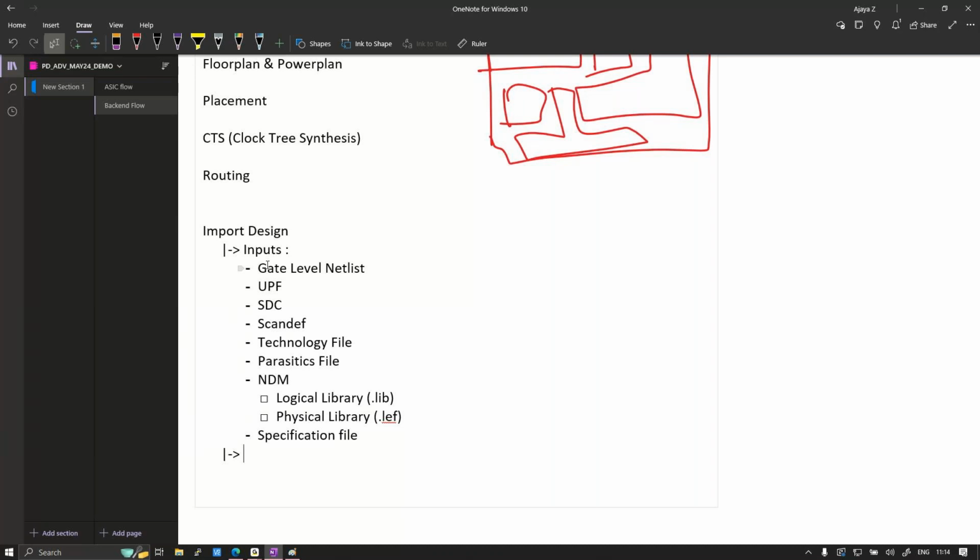So if we have any issue, the first step is to go through the log file. Observe each and every error, warning, and informational message also, because some informational messages need to be focused on. Errors and warnings have high priority, informational messages less priority. This is only for your understanding, you don't need to report it. Knowing it is better, so that we get to know what is happening in those stages.